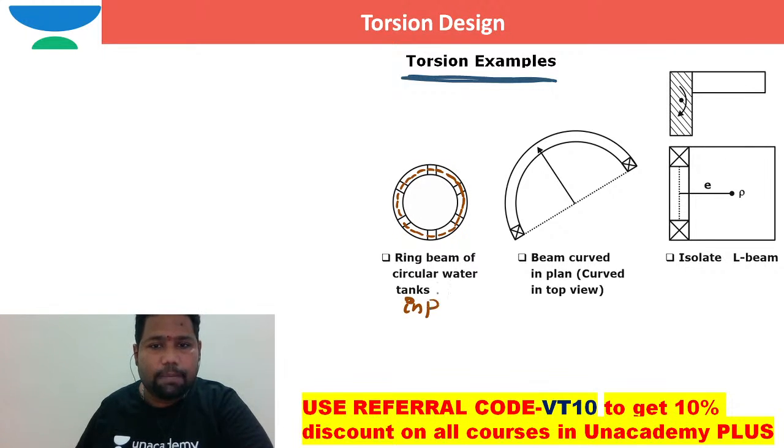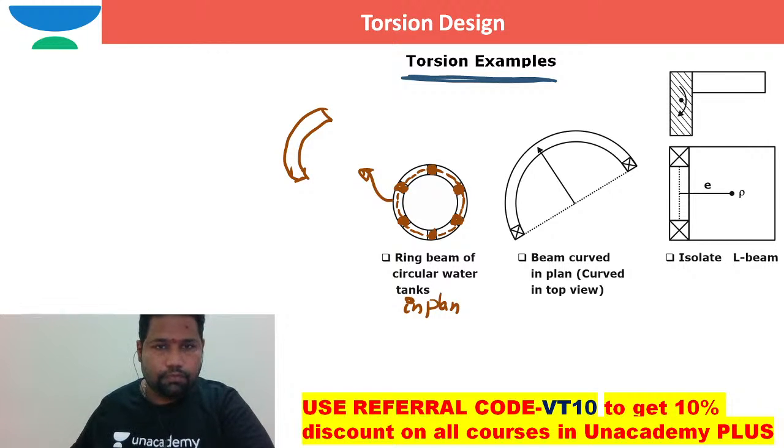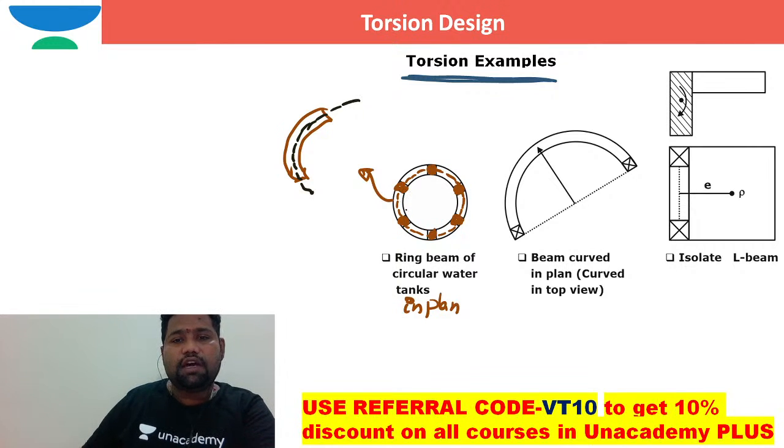If I show it in plan, these are columns. If you take a small ring beam, this is how the ring beam is, and this is the centroidal axis of the member, where the total load acting on this entire ring beam will be acting here.